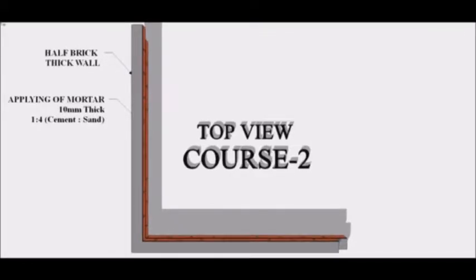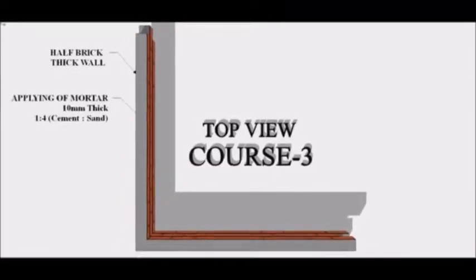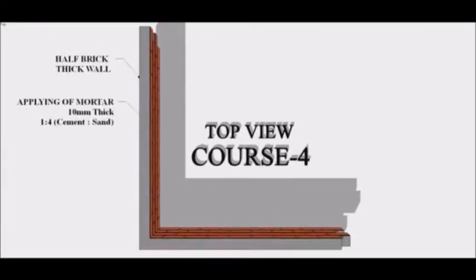With a similar process, other courses in the wall are laid. Courses 1, 3, 5 are the same in the 6-course wall shown here. Similarly courses 2, 4, 6 are the same. Stretcher bond is also known as running bond. The waste in this bond is less, as it does not require any header.